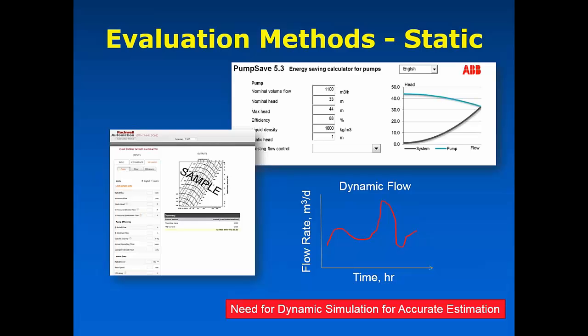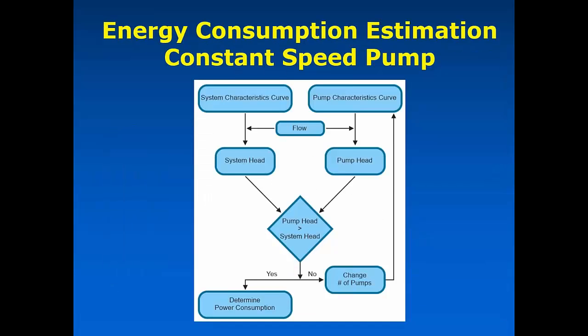So we have a need for an accurate way to assess the change in the dynamic head as it moves around at different flow rates. So what we've done is we've put together two separate flow sheets here that describe the way that we choose how many pumps are going to be in operation at any given time.